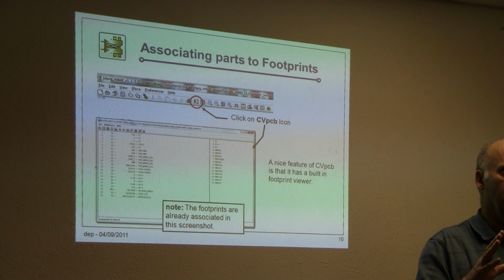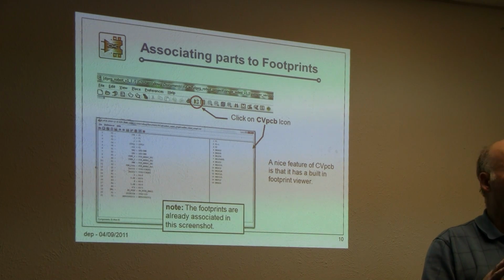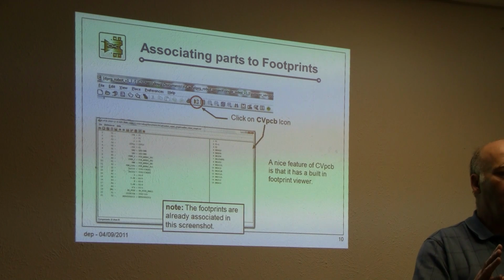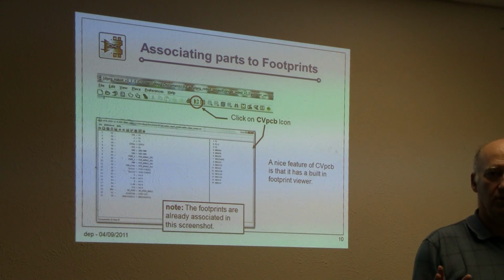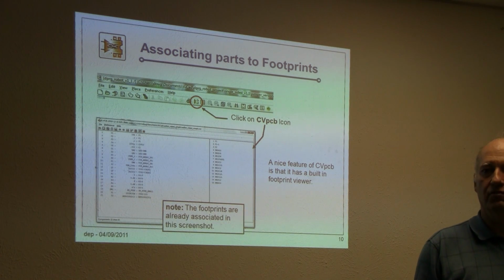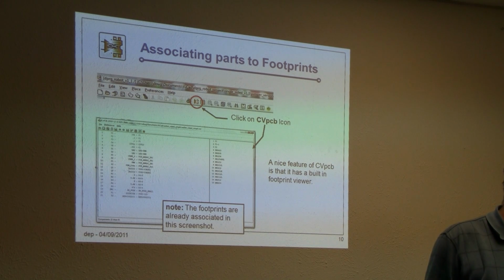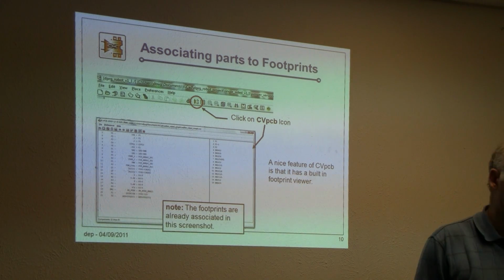It's sort of a drag and drop kind of, but it's not a copy and paste. You have to use the right mouse button to copy it. Then you can go to a totally different sheet and do a paste type operation, and it will bring that into the new schematic. It's very nice. You can also do something like that if you want to have on the same page 5 copies of the same circuit, or similar to the same circuit.